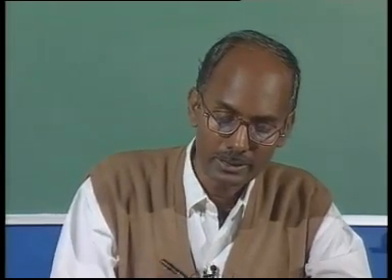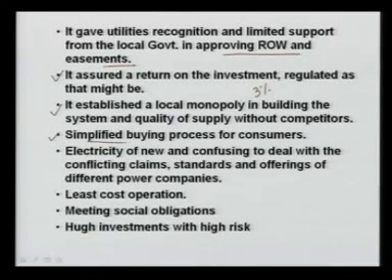But in this competitive era, it is totally different. Like in the UK, every half an hour the price is changed. So it is very difficult to monitor what the rate will be, and since you may be in office, how are you going to consume? The price is changing half hourly or hourly in the competitive mode, so it is very difficult. You have to go for time-of-use meters so that you can pay accordingly. Here in the regulated market, this is very simple: consumed energy multiplied by the rate is what you pay.